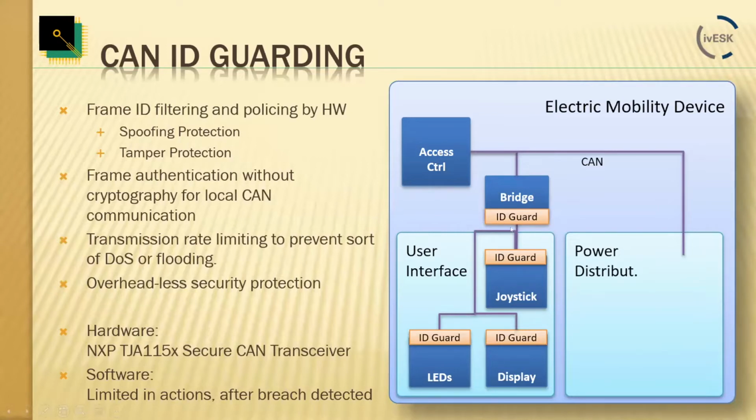So if each of these devices monitors the network for CAN IDs that are supposed to be reserved for them, then of course, as soon as somebody injects a message here, somebody here will recognize it. Now, the big question and difference between hardware and software implementations is the what then? What then meaning we detected it, so now there is the message out there. How do we react to it?